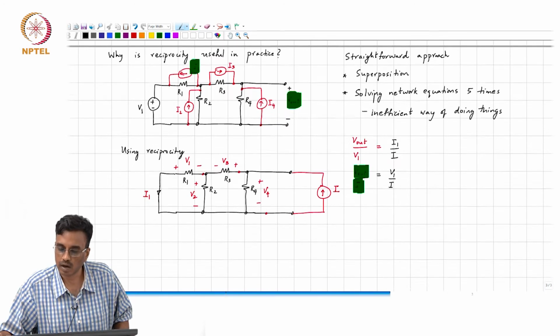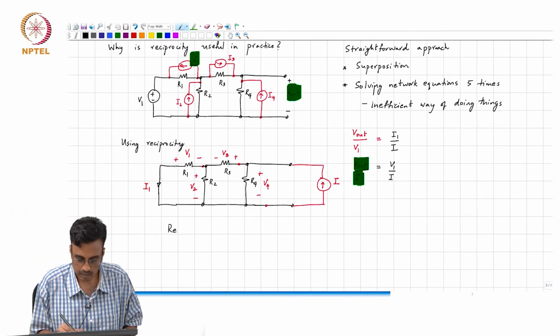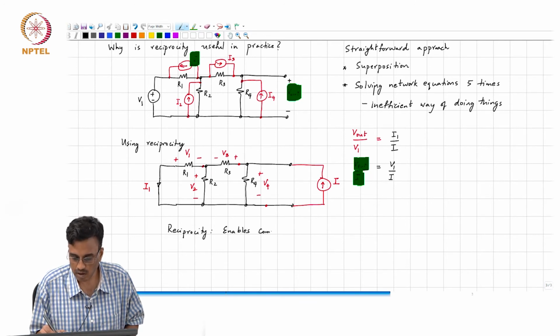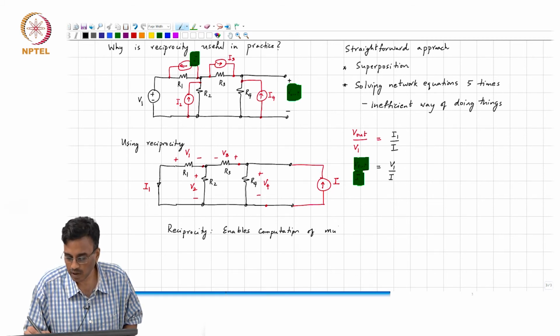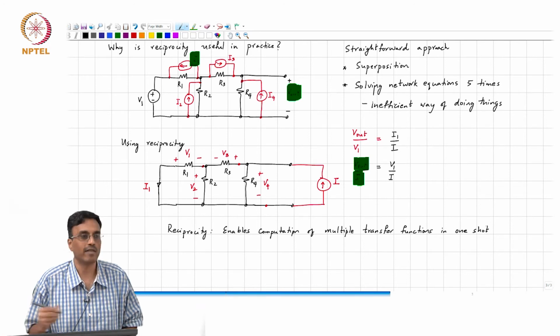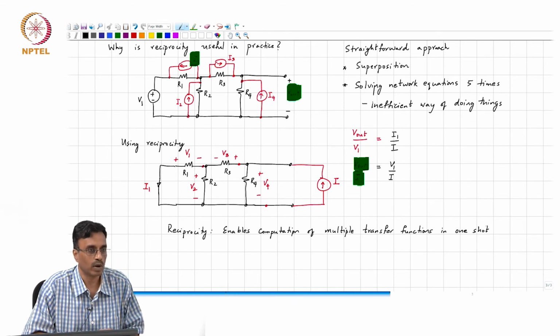And therefore, this reciprocity enables computation of multiple transfer functions in one shot, without having to do the solution of nodal equations one by one by one by one.